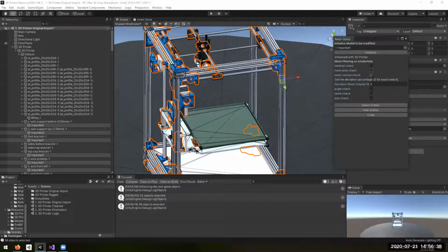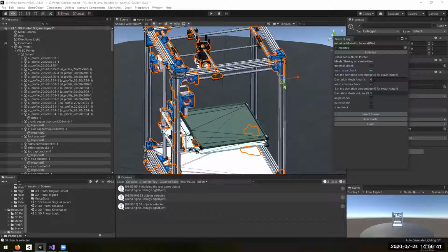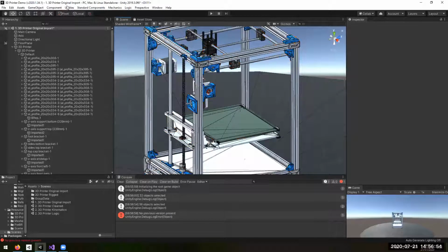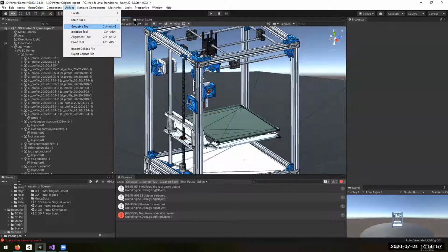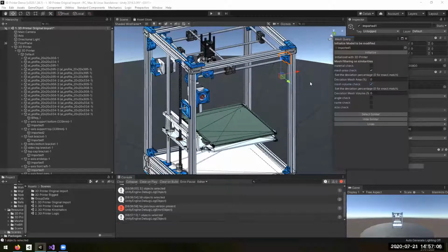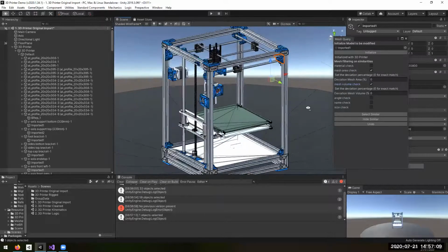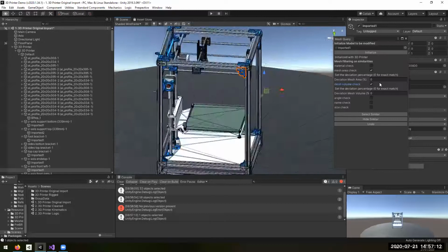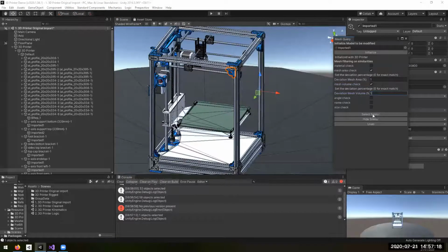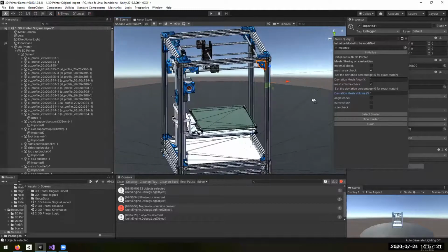So if I select the mesh area and the volume, and let's say I don't want to deviate anything, okay, wait, I'm going to reopen this because it had everything selected already. Mesh tools, mesh query, mesh area, and mesh volume, select similar. Oh, it doesn't find anything similar. Let me change it to 1% maybe. Select similar. No, it doesn't find anything similar.